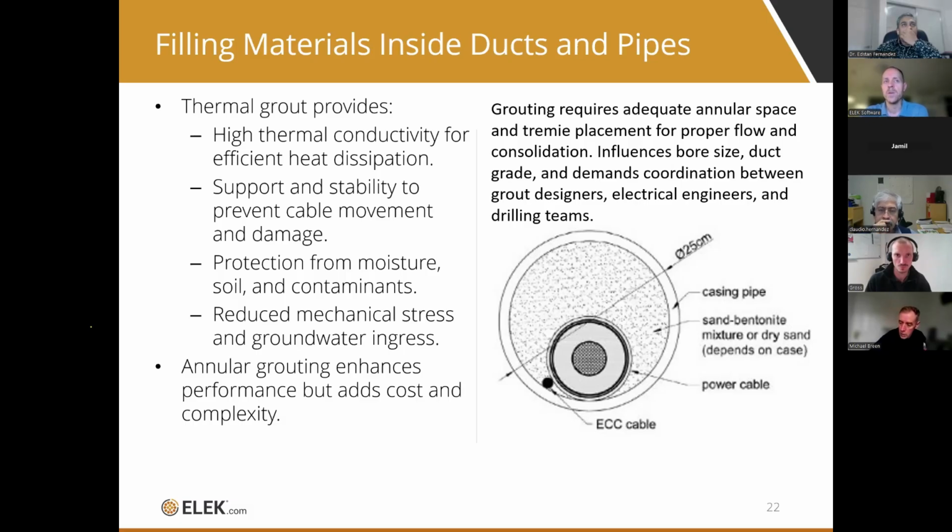Adding grout to the cables improves performance, but it adds cost and complexity, and you need to provide larger ducts to allow space for installing these materials.